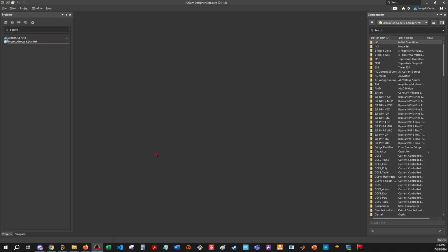If you're not too sure what Gerber files are, they are CAM documents, which stand for Computer Aided Manufacturing, and they tell fabricators exactly how to produce your design. So for a board, that means they can see things like your copper layers, how the traces are routed, any notes you have in mechanical layers, and even the drill locations for your drill table.